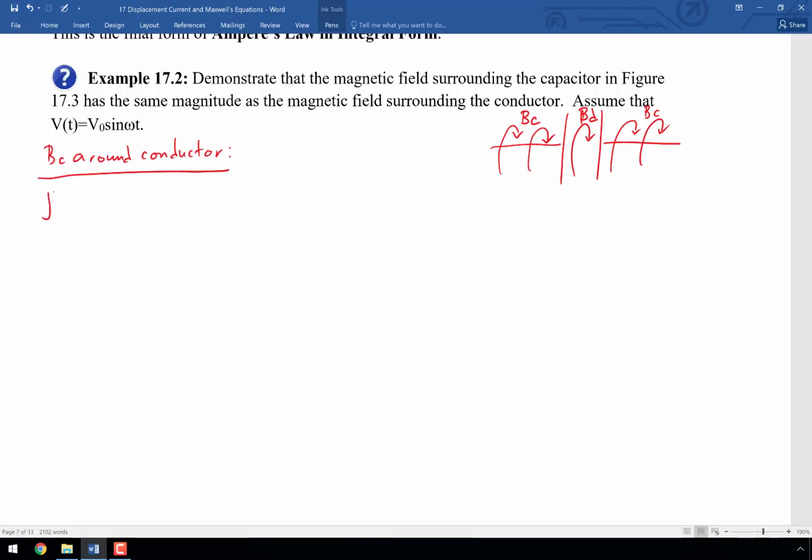I'm going to take the full form of Ampere's law: the integral of B over mu sub 0 dot dl is equal to the surface integral of J plus the partial of D with respect to t, integrated over a surface. Since we're around a conductor, we aren't going to have any displacement current, so that term goes away. Let's specify that I'm looking end-on at the wire, trying to figure out the magnetic field around it. If this is B, then the distance out there is rho.